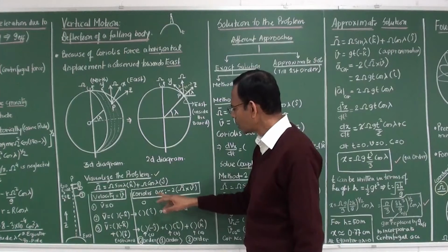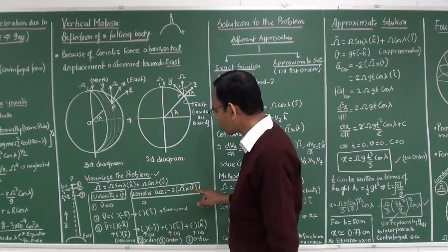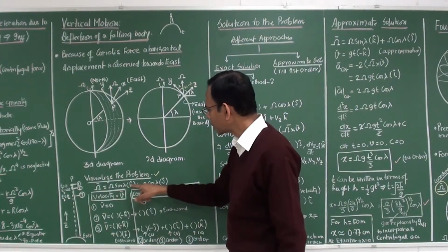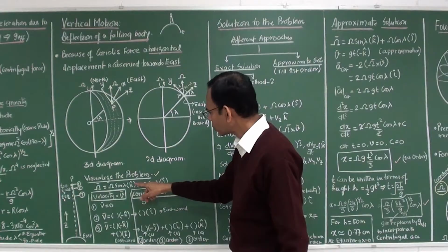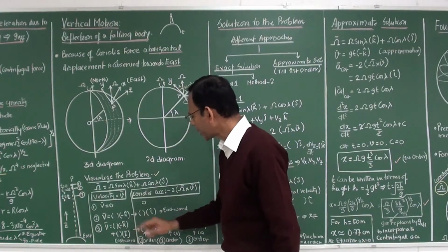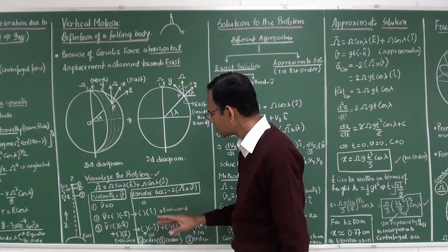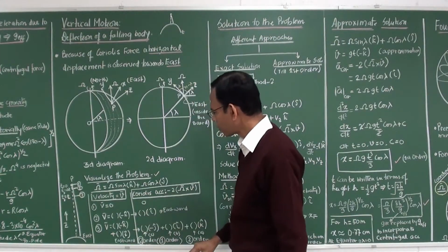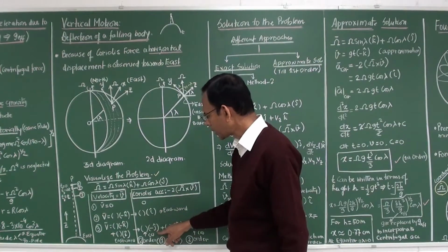Now let us see what is the Coriolis acceleration. Again omega cross v, where omega has k cap and j cap components. k cap cross k cap is 0. k cap and i cap, that is k cross i, is j, but again there is a minus sign, so it is minus j cap.